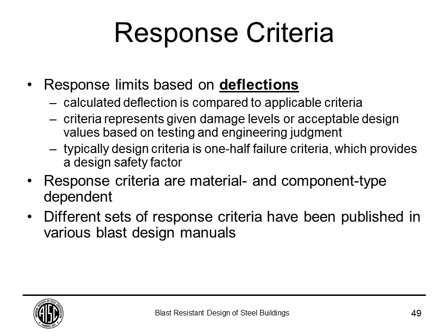And now we want to talk about the response criteria, which is when we compare the response to the acceptable limits. The response limits are based on deflections. Typically, you compare the calculated deflection of your member to the applicable criteria. These response limits change based on the material and the component type. There are different sets of response criteria, but for the most part, the typical designs, VA, Department of Defense, and federal facilities all refer to the PDC TR-06-08, which we're going to see an example of what those tables look like in 3 or 4 slides.